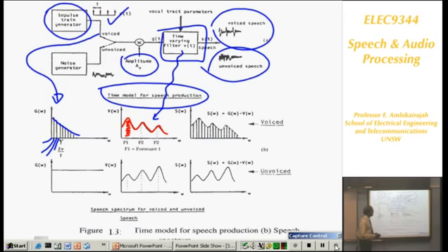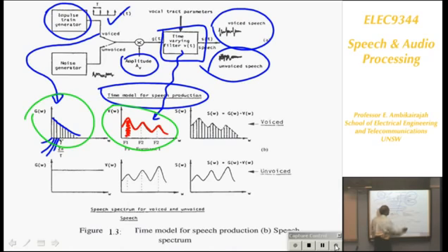If you take this spectrum and multiply that spectrum in the frequency domain, then this is your output spectrum. So that's what the multiplication is showing. You have done that. If you have a cascaded system, in the time domain they convolve, in the frequency domain they multiply.